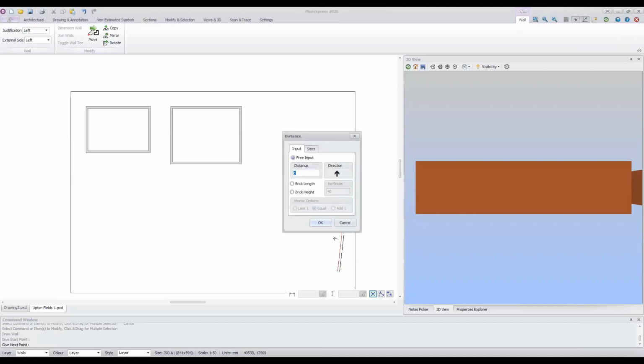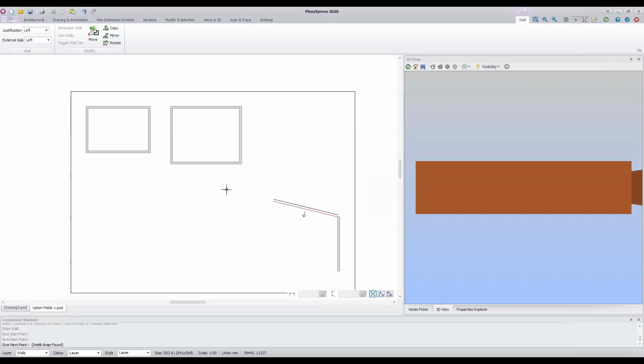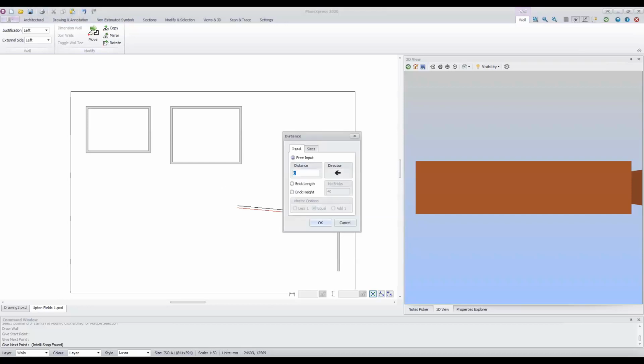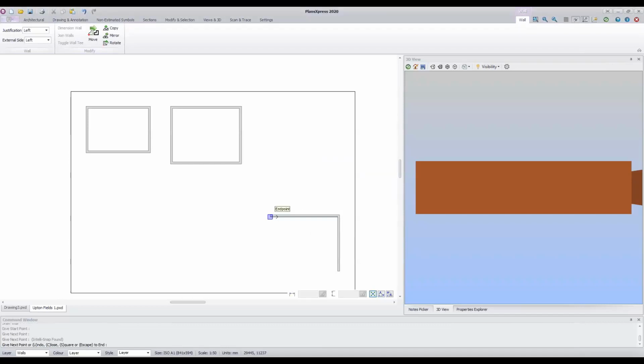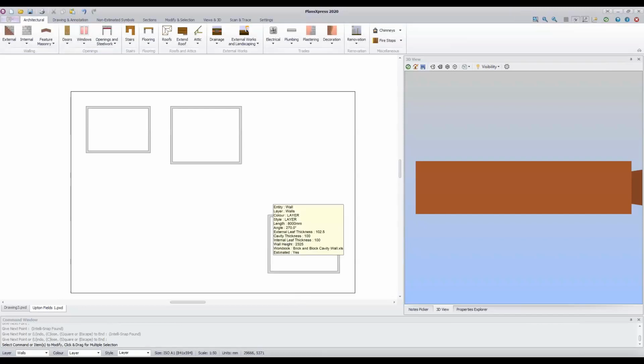Let's say we want to go up. Just draw another rectangle, whatever dimensions you want to type in of a fairly typical house. So type in the distance, press the return key on your keyboard, press across, so across to the left, say 10 meters wide, 10,000 mil. And then at this point you could press the S key, couldn't you, to square off your walls. So using those shortcut keys, it obviously speeds up your work.